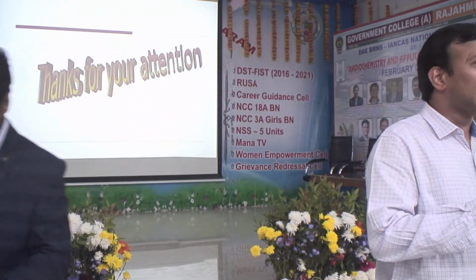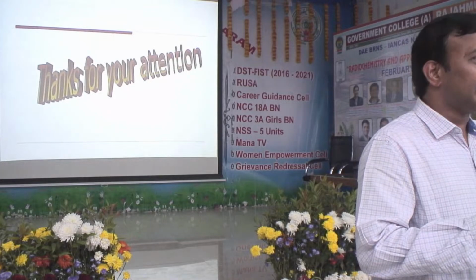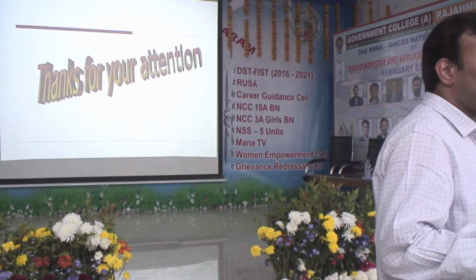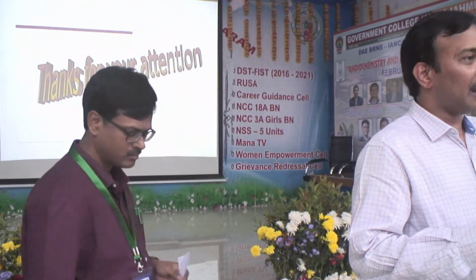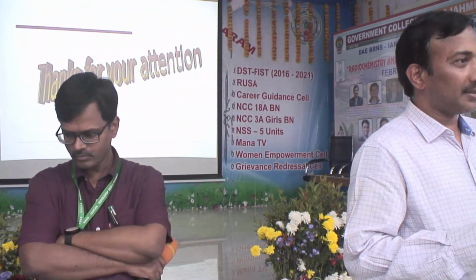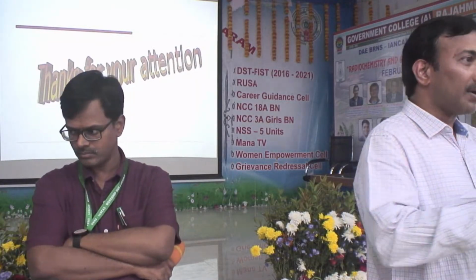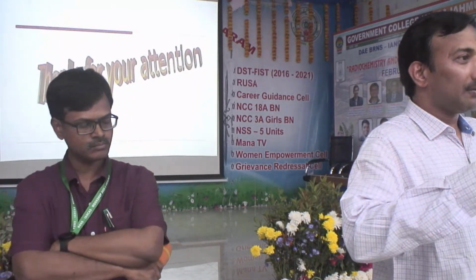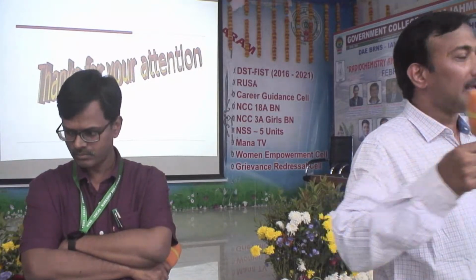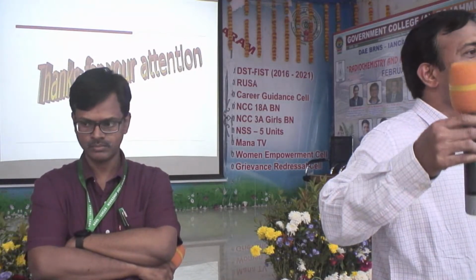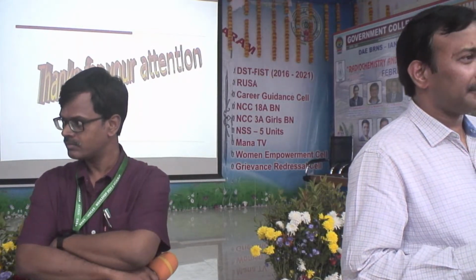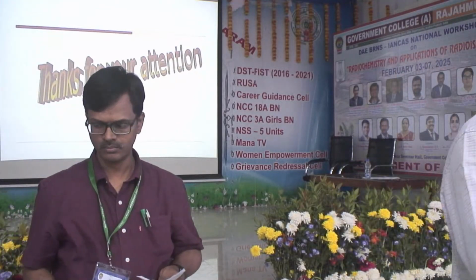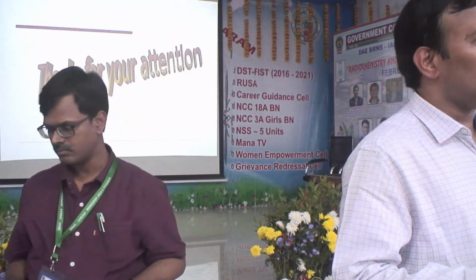They take uranium oxide powder and make the pellet form by compressing and then sintering. Finally, as I have shown in the picture, they get pellets of around 1.6 centimeter diameter and around 2 centimeter length. The pellets are encapsulated in a clad tube. Imagine one very thin tube, Zircaloy-4, and they add the pellets one by one and then seal it. That's the clad preparation. So Zircaloy-4 is the clad tube and uranium oxide is the fuel material.